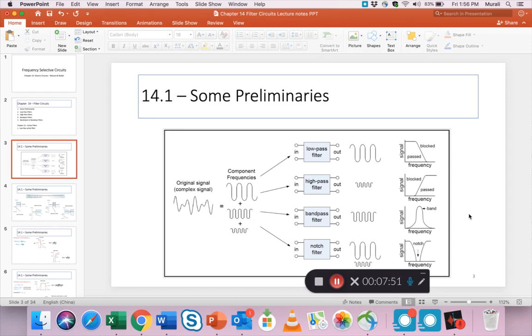So that's what you see in the middle there, where it says component frequencies. What it's telling you is that the original signal, which has a number of frequencies and a number of amplitudes, can be thought of as having roughly 3 main components. There is the primary component, the lower frequency and large magnitude, generally called the fundamental component, and the other 2 you can consider as harmonics or additional components. If you add all 3 together, ideally you get the original.